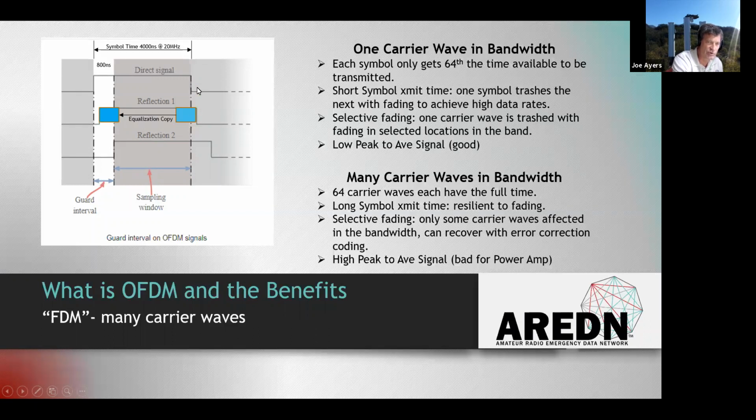It's starting to push out into the guard interval of the next symbol over here. And maybe I have another reflection path and it's pushing out and fully consuming that next guard interval.